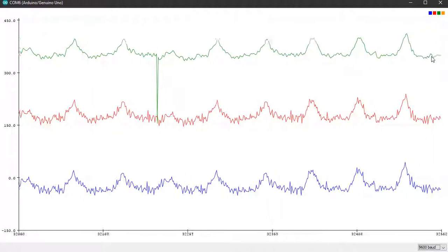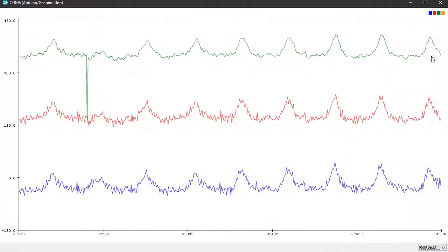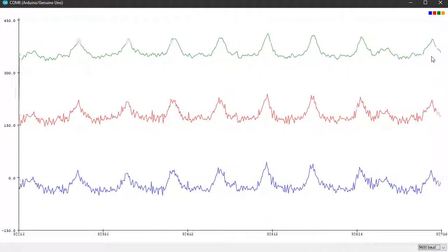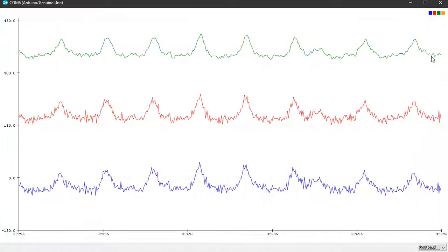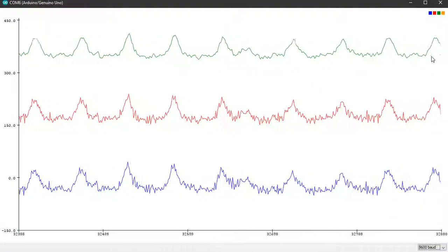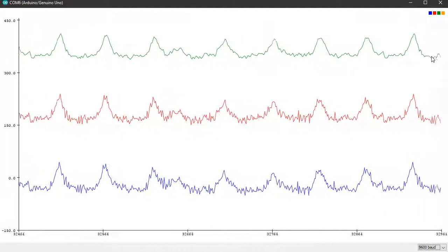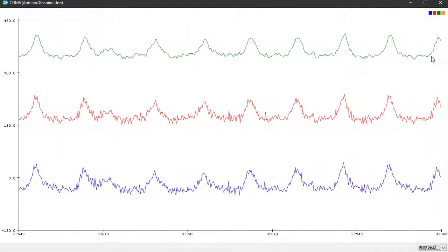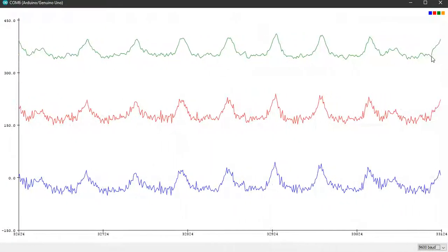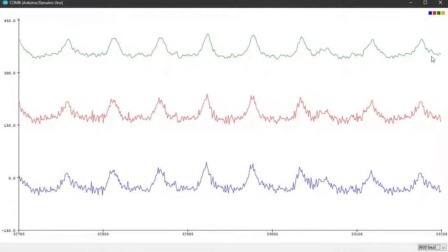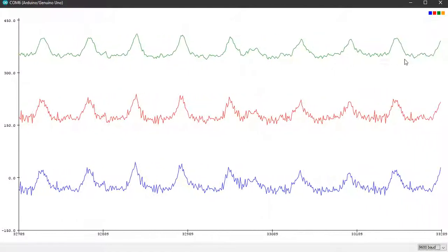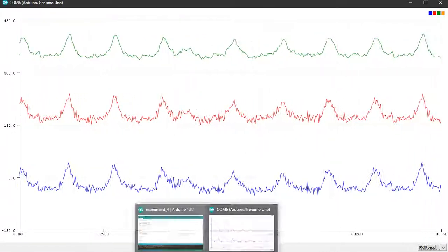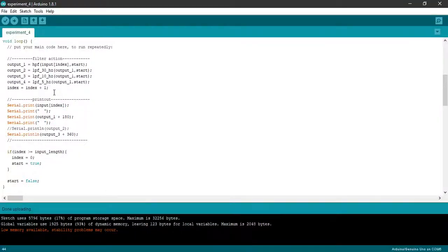We still need to smoothen out more noise, as the heartbeat signal that comes out in the PPG signal generally is in the range 0.5 to 5 Hz. This is the entire range for our heartbeat signal. So the rest can be considered as noise. So let me show you the output of the next filter, which is at 5 Hz.